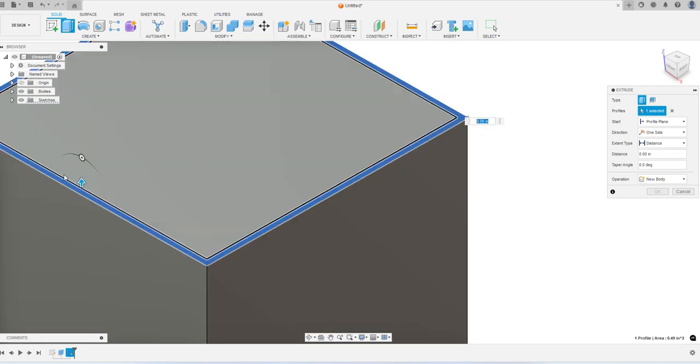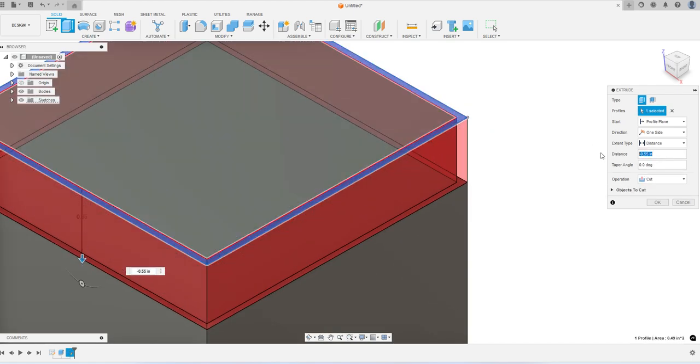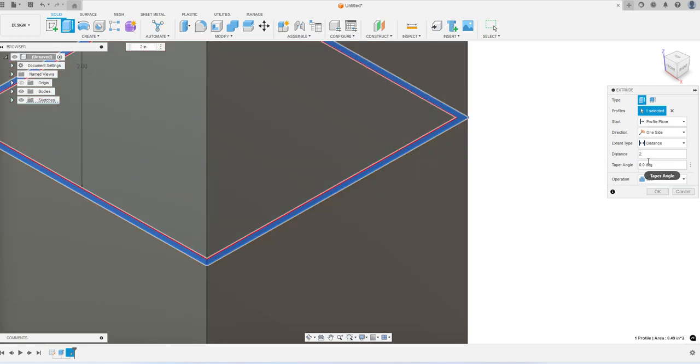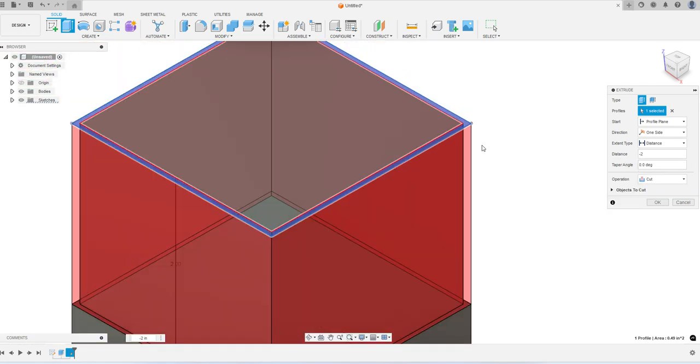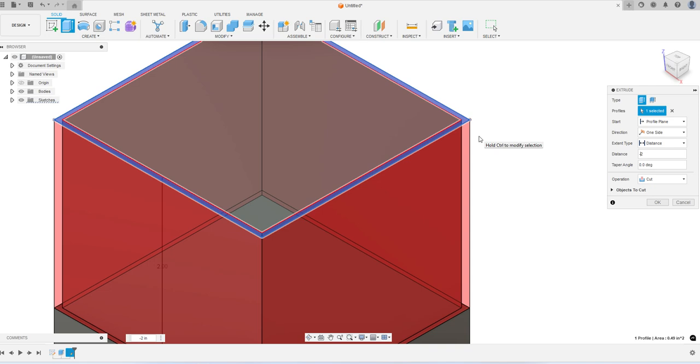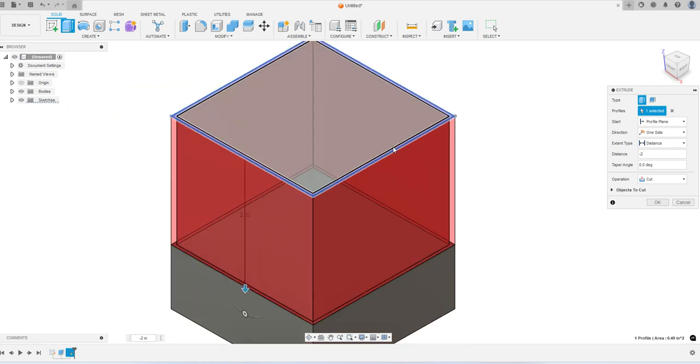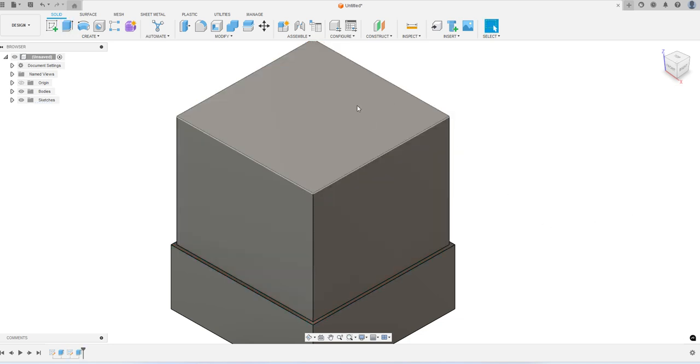From there, I'm going to finish that sketch. We're going to have a lot of sketches, and what we're going to do is try to cut things out to remove more and more material, so that we can, in a way, simulate what could be done for our actual process. This is not the most efficient CAD modeling process, but it is one that usually results in the fewest mistakes. From there, we have the actual material that we are going to cut out of.